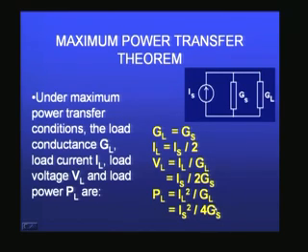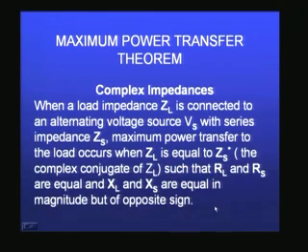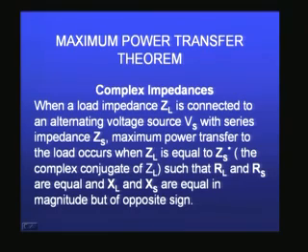So this is the law corresponding to constant current sources when you employ and look at the maximum power transfer theorem. There is also another case where instead of DC you can think in terms of AC circuits. When you have AC circuits, you will not only have simple resistors, you will also have reactances or impedances, for example capacitive reactance or inductive reactance. So in general you can call them load impedance, ZL.